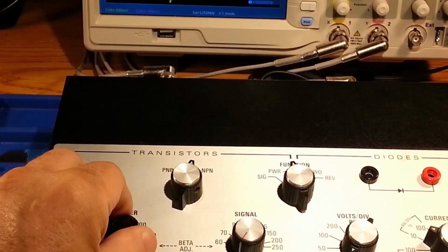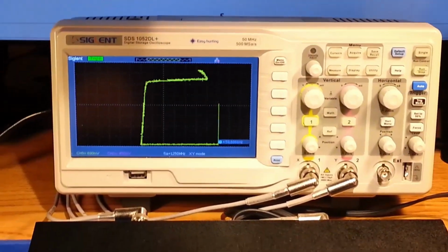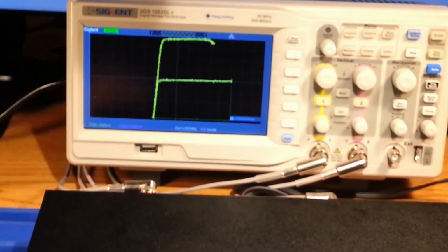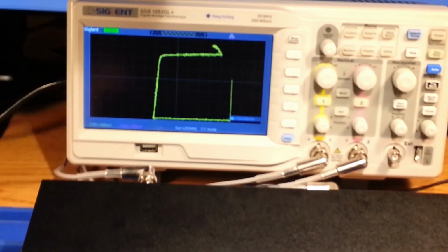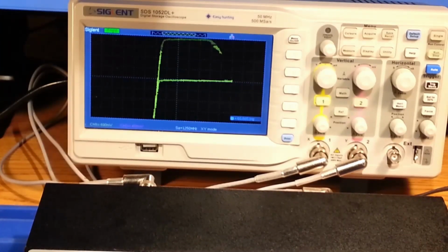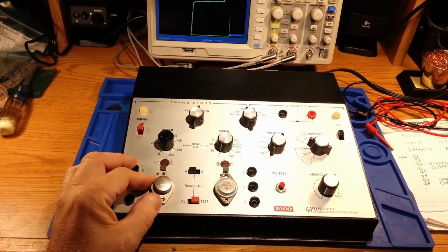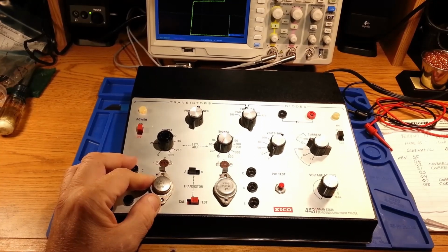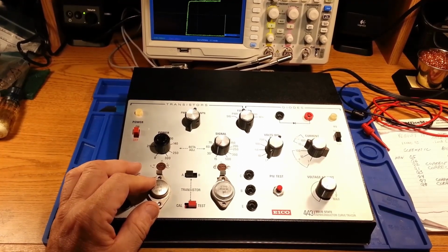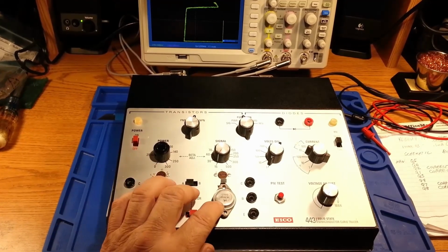So in this case, I can take the power adjustment knob on the unit, which is this one here, and in order to figure out what your gain is supposed to be, you adjust it so your sweep goes the full 8 vertical graticules. And in this case, on this unit, it's about just above the 140 line. And I have 2 transistors in here. These are pulls out of, I think, some Dynaco ST120 amplifiers. This one is one of the audio output drivers, and I believe this one might be for the power supply, which is supposed to be a very low gain transistor.